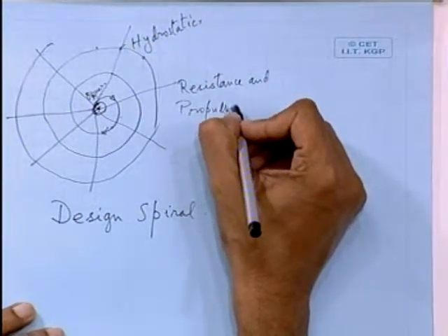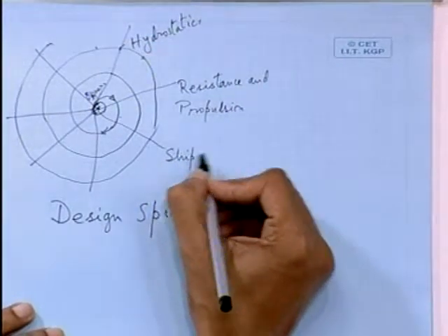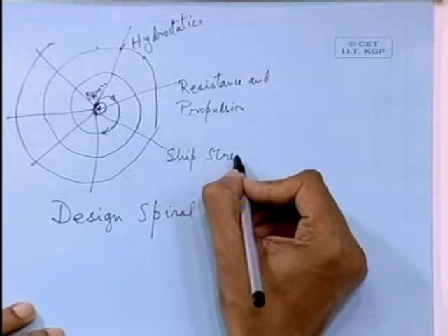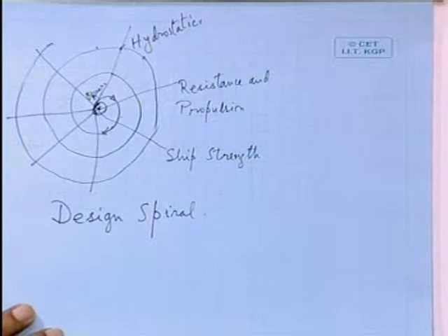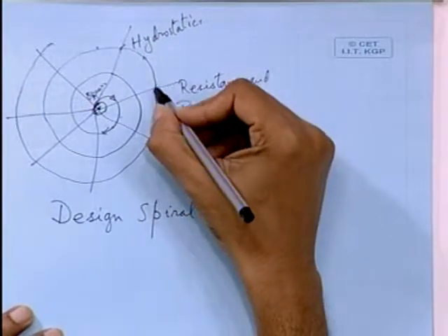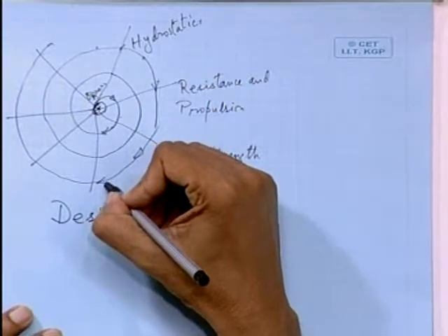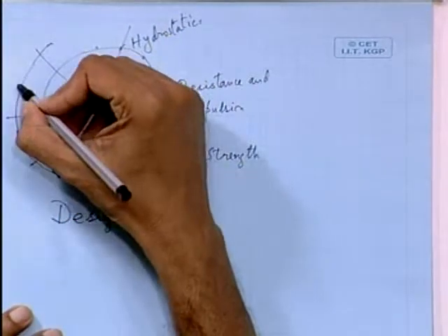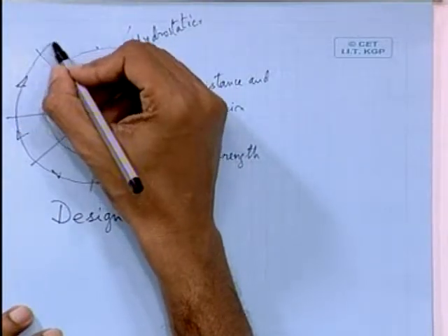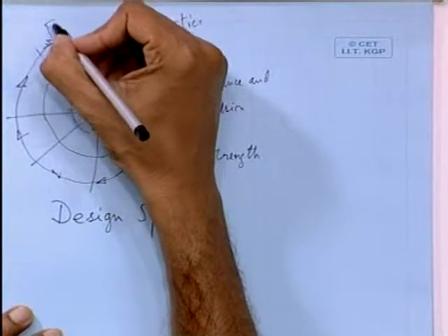So next may be your structural, your ship strength. All these calculations are made by varying your initial parameters governing the lines plan, that is your length, breadth, depth, draft. And of course, there is a constant check on all this, that it conforms to the classification society rules, that you see a ship that is being built, from the owner's specification it comes to the final design.